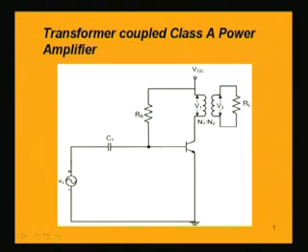If we consider this collector current, as there is no resistance, the current will be almost infinite, and the voltage is VCC. Because we have to know the maximum values of the collector to emitter voltage and the maximum value of the collector current to draw the DC load line, if we consider this circuit on the collector side of the transistor, the VCE maximum value is the supply voltage VCC.